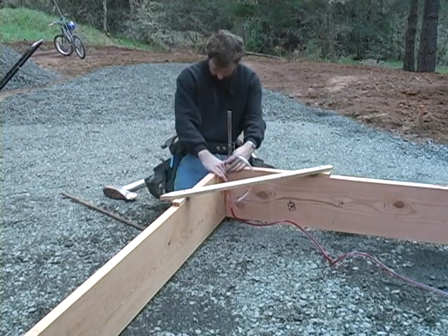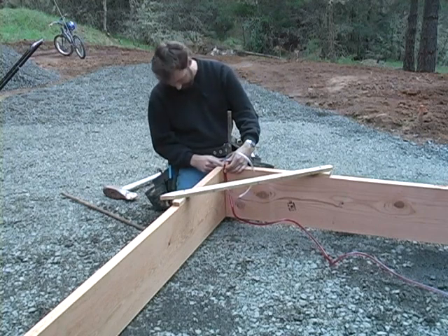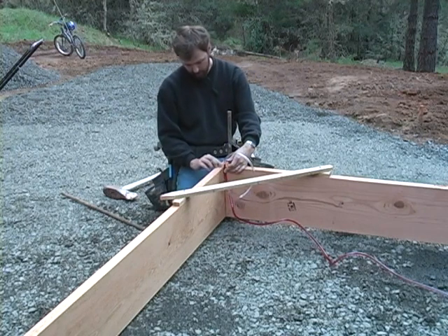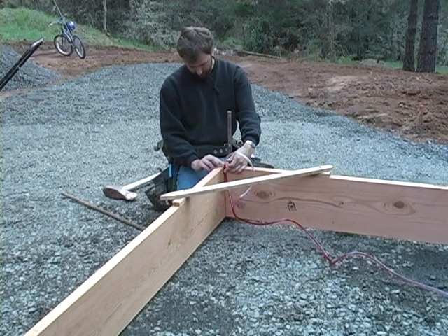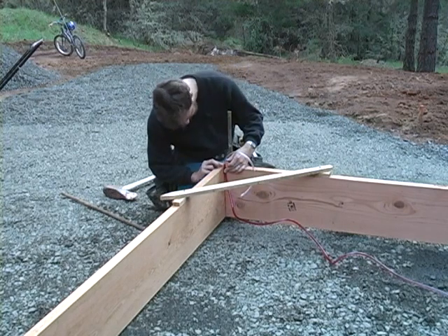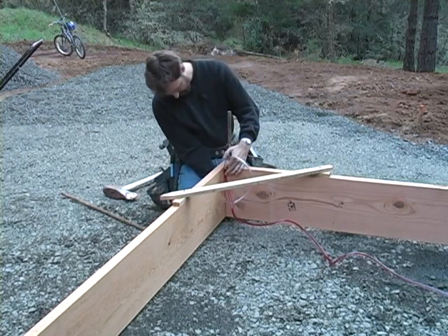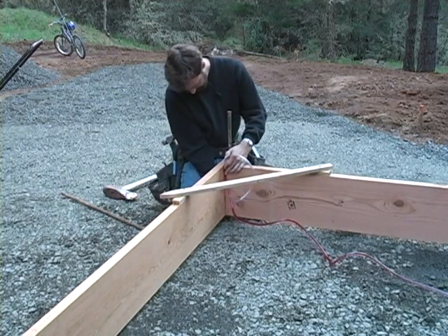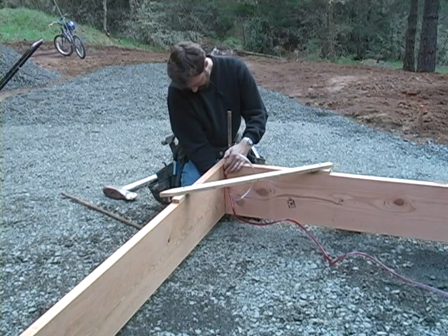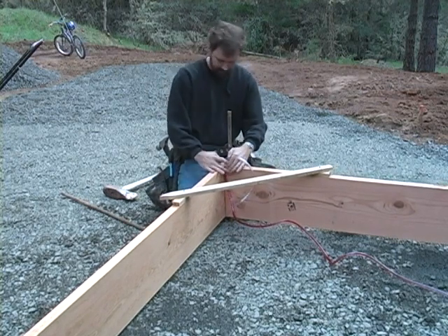Now as you can see here, I'm about a 1/2 inch low. My form board is low. The top of this water line right here where the red is topping out is the top of the form in the corner that I'm using. So what I'll do is I'll bring my form up until I meet that spot, and that's where I drive my screw.